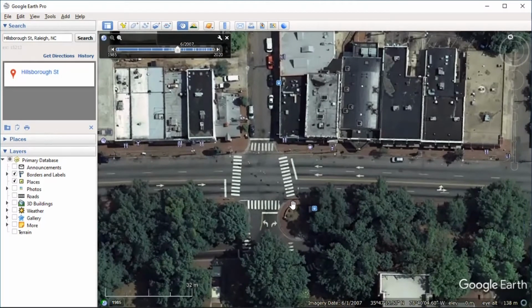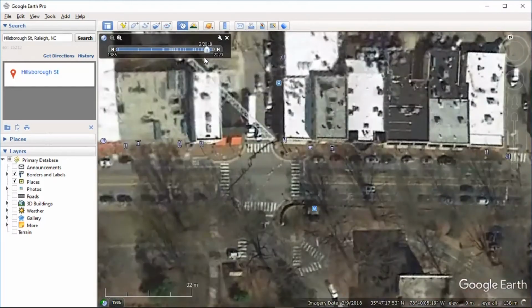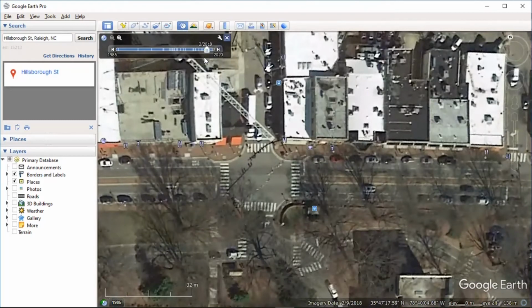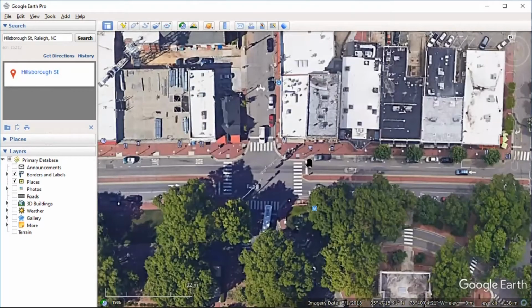So pedestrians, they have to cross all these 4 lanes. Okay, now they wanted to do a traffic calming, so they came up with that situation. You see it now? So now the distance that the pedestrian is crossing is significantly lower than before. And now we have only 1 lane crossing. We have parking for cars here, and this way you are forcing traffic to avoid driving through here, and if they are going to drive here, they are going to have slower speed. Okay, so that's what we mean by bulb out.